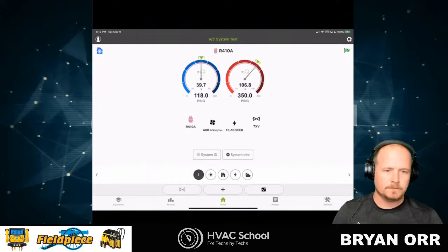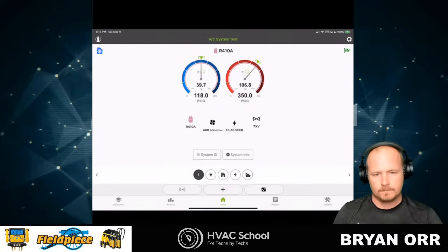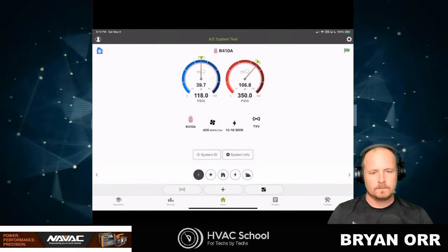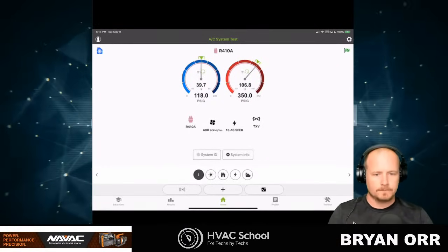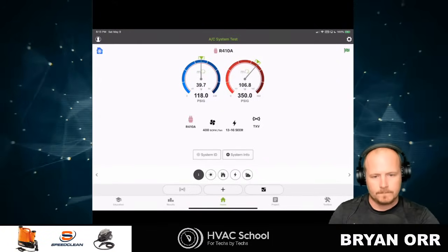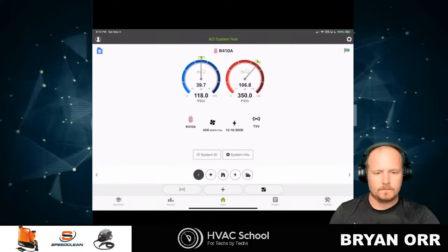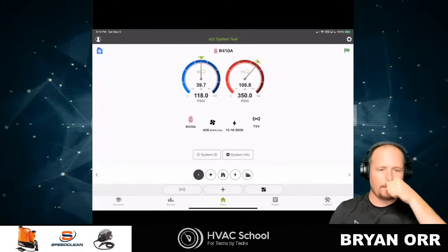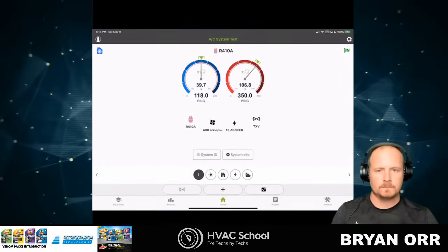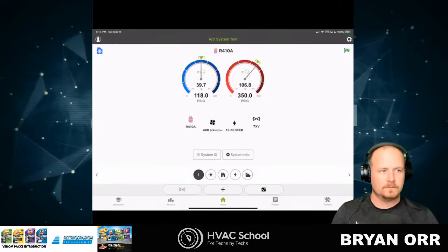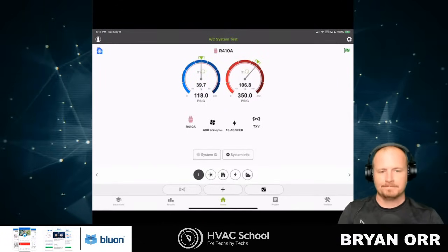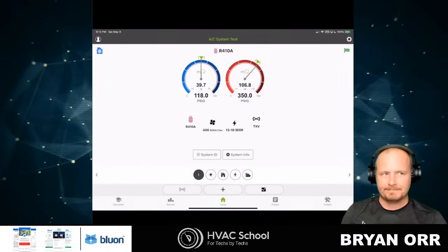We have a starting point, which is what's on the manufacturer's label, but if you really want to hone in on how that piece of equipment's ideally tuned, then the benchmark is a way to document that. And then going forward, you don't have everybody tweaking the system to what they think is the right way it should operate. Everybody in your company is using the same baseline for performance, and everybody understands very thoroughly how that equipment's supposed to run, and everybody's taking it back to that benchmark every time it's serviced, right? So it just makes it a lot easier.